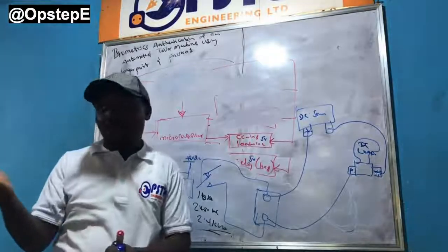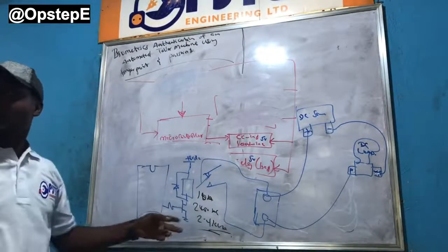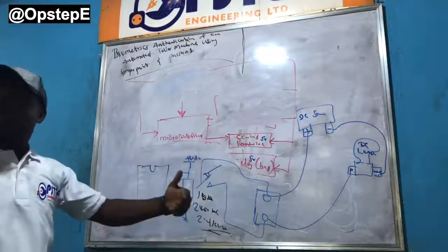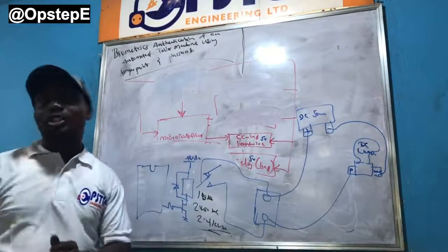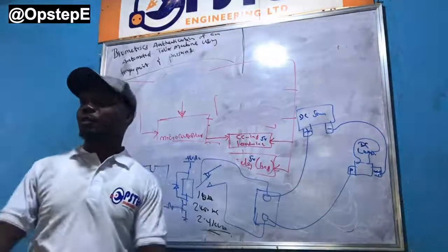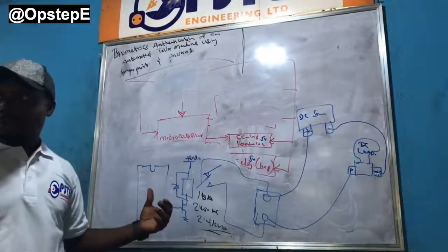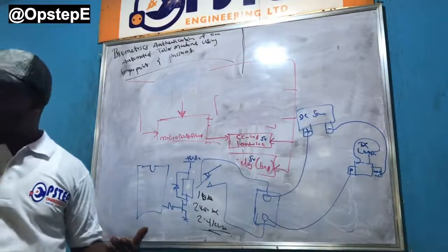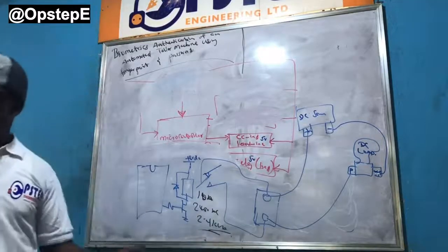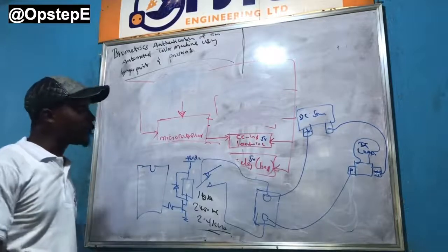They're important. The same thing with the battery, when we're using a diode to block back EMF on the battery. Imagine the battery is 1,500 volts. That diode will go bad because it will exceed its avalanche voltage range and be damaged. You get it? Which of course is your reverse bias voltage.